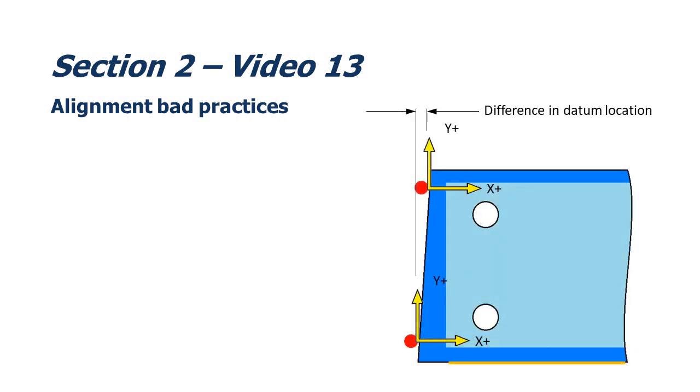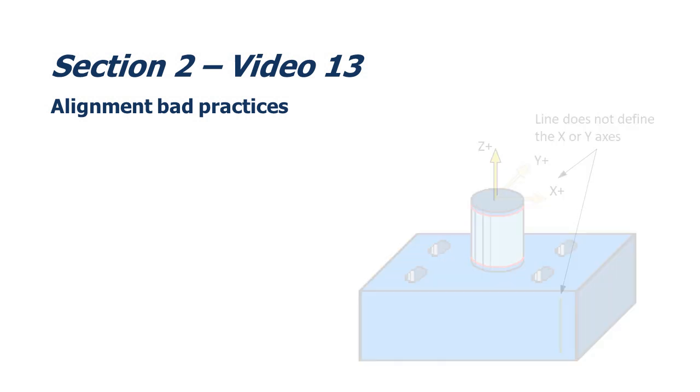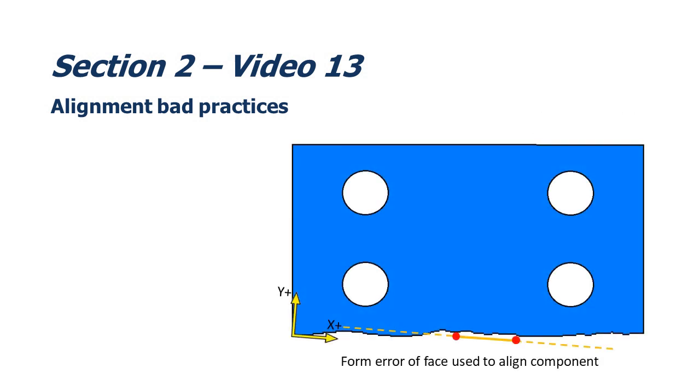These include the effect non-square faces and form error have on a plane, line, point alignment, why selecting concentric circles doesn't work when setting a rotation, setting the rotation to the same axis as the first axis, and when the alignment is rotated about the incorrect axis. We'll also look at the effects of using a short length to set the rotation, and the measurement errors caused when an alignment hasn't been created and work planes haven't been set.